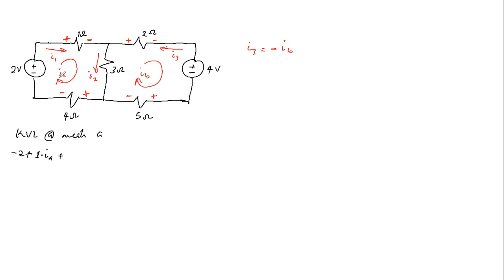plus, now I2 flows into the 3 ohm resistor, and you see that I3 flows in the opposite direction. So if we say here 3 IA, since IB is in the opposite direction, so that will be minus IB. Right in this branch, because we have 2 currents flowing in this branch, IA and IB, following the mesh current direction rather.